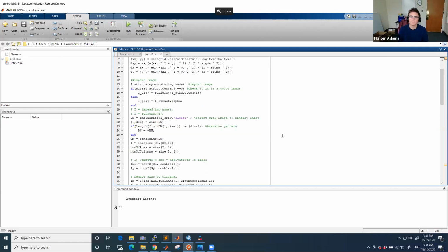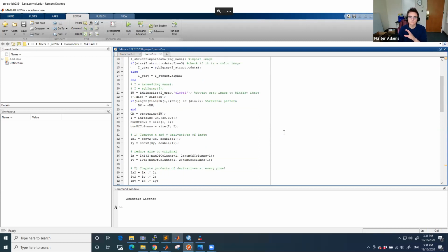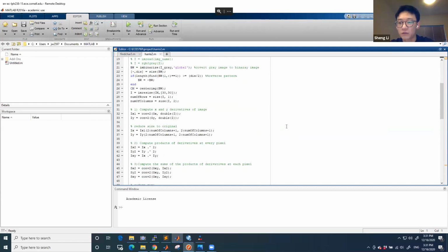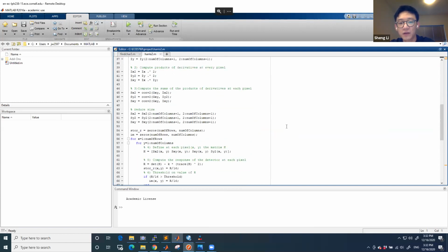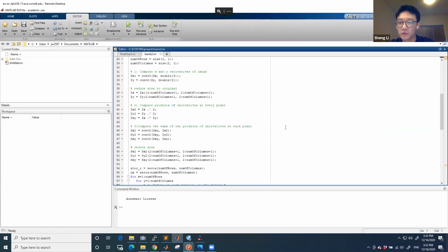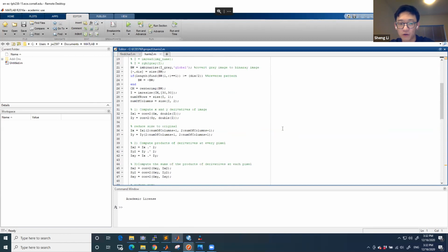Oh, okay. So you just give the FPGA the image, it does the filter, and it will tell you which letter it is based on the output from a corner finding algorithm that you've also implemented. Yeah, we did a KNN-like algorithm and a voting algorithm to do the prediction. Sam can introduce that more.